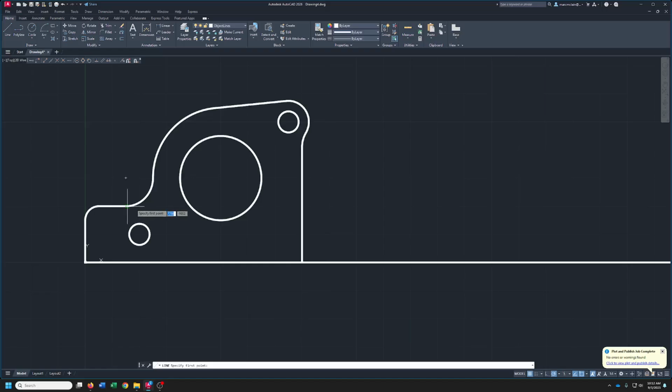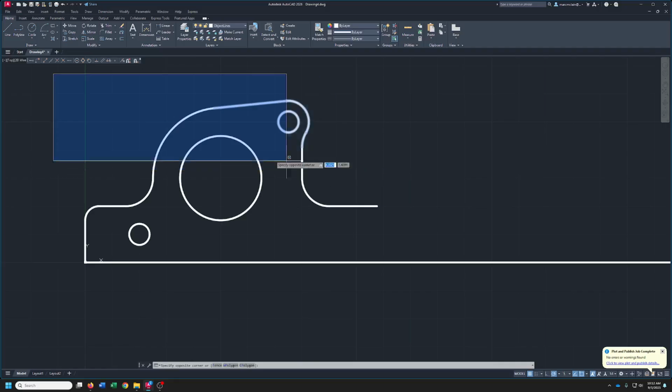Now, I'm going to line up with this. And I'm just going to draw a little piece there. Now, our fillet should still be set. Double check. Yep, it's 0.5. Just hit enter. Pick here and pick there. There's your first one. Now, if you look, you see the distance between the two is 4.5 until we get to that very last hole. But 4.5 is generally what's going on.